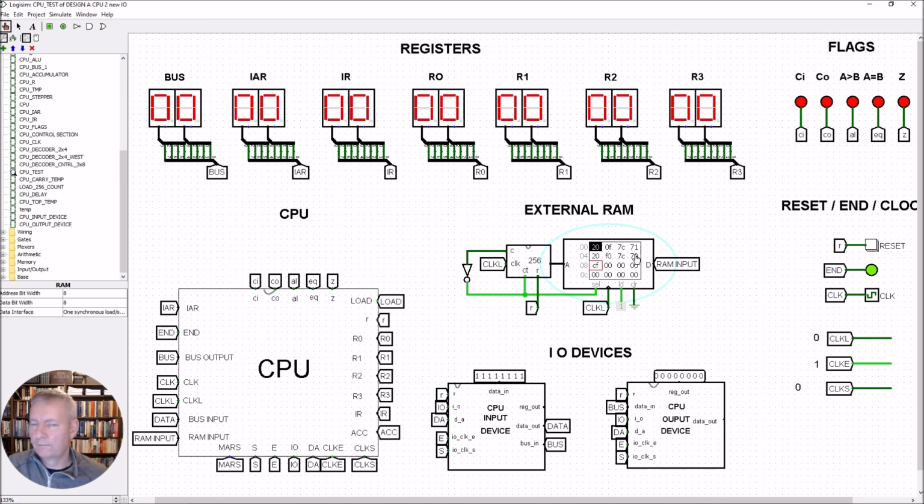Okay, so you can take a note of those and you can try this out for yourself and you can work through it one step at a time, but I'll just simulate now. So simulate, tick enable. So if it works out, it should take the 111, put them into a register up here, read out this register and then put it into the output device. And there you see, that's it, done it now. It's taken the value FF which we've typed into our keyboard, it's put it into a register up here, R1.